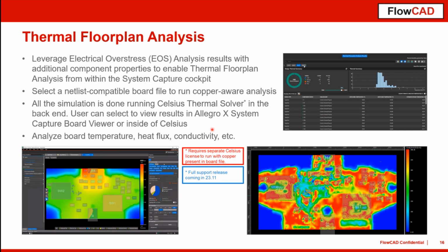So let's move them away a little bit, or at least try to move them away a little bit, so that the thermal floor planning is a little bit optimized in this case. So yeah, you can open the board inside of System Capture, view the board, have a review inside of System Capture, and also do this kind of floor planning. I will show this a little bit later inside of the tool. And we have lots of additional analysis possibilities in the PCB context here.